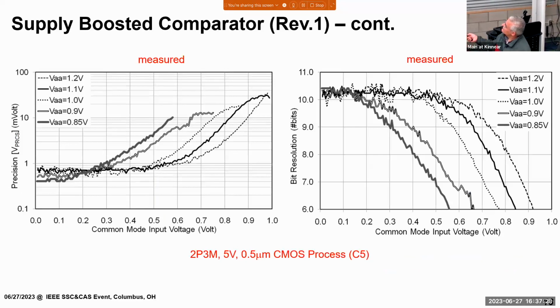That's why you have this range. The range kind of drops a lot, right? So at 1.2 volt, you can go maybe with 10-bit resolution, maybe 0.6 volt with 1.2, which you are boosting to 2.4 volt. And there you don't have really issues with different input ranges. But if your supply drops too much, that is going to affect that decision point and your input range for sure.